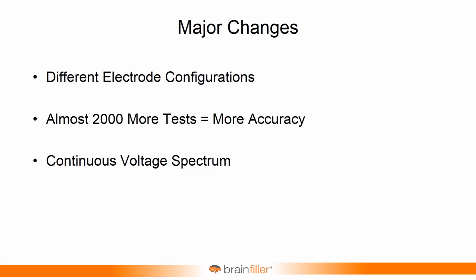But the 2002 edition, the arcing current was really based on just two equations. There was an equation that went from 208 up to 1 kV, just under 1 kV. And then there was an equation from 1 kV up to 15 kV, and that was it. So pick one. And there were no adjustments or fine tuning for actual voltages. That's all we had. So the new one, we widened it out. There are 3 voltage-based equations. There's 600 volts, 2700 volts, and then 14.3.